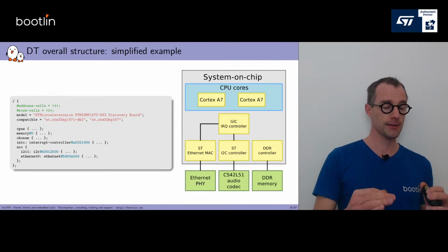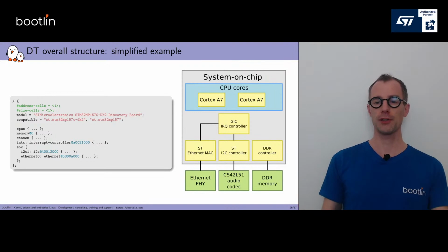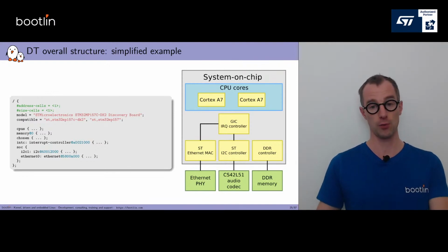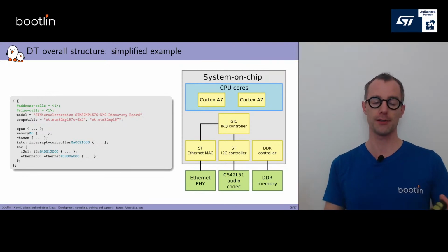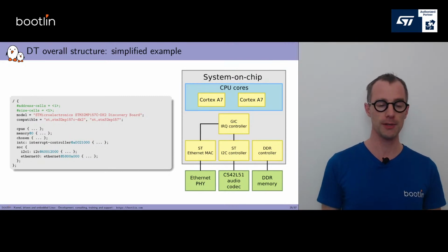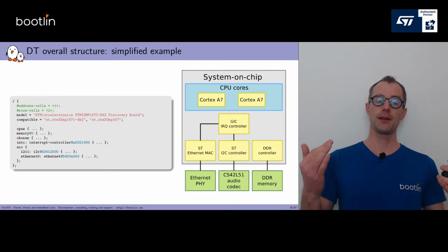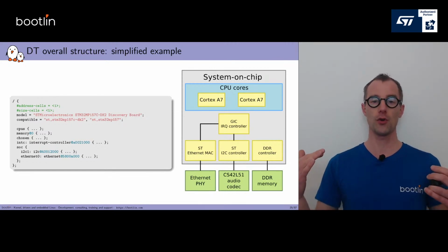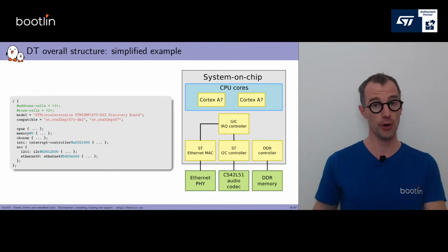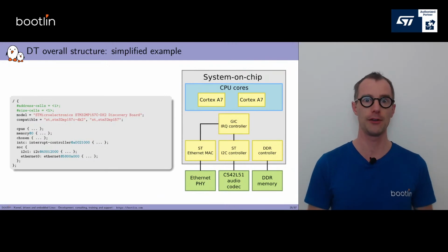And then the next nodes, some of them are specified by the device tree specification itself, and we're going to discover that later, and some of them are described less by the device tree spec itself, but by other documents. It starts with defining the CPUs, then the memory, and then a node called chosen, and then we have a number of nodes describing hardware blocks. So I'm going to go step by step through all of those top level nodes.